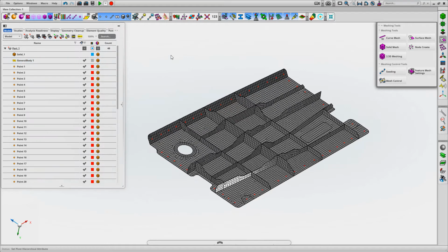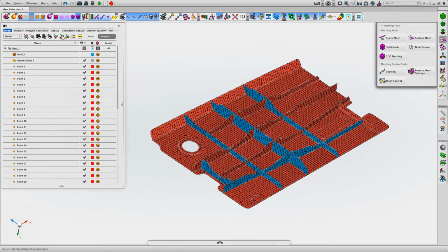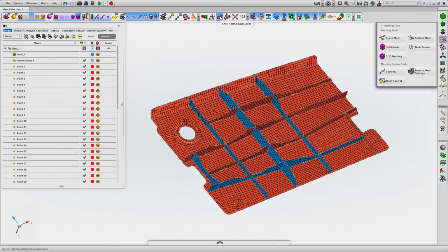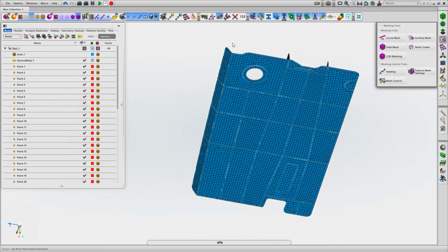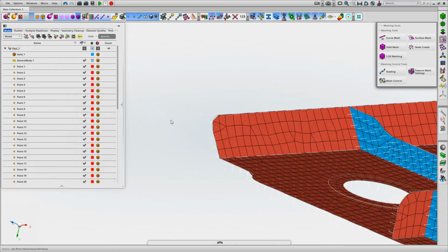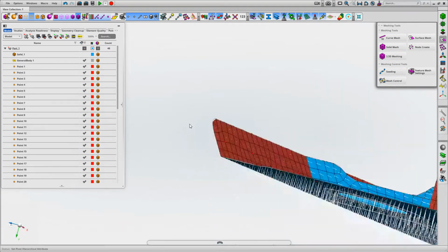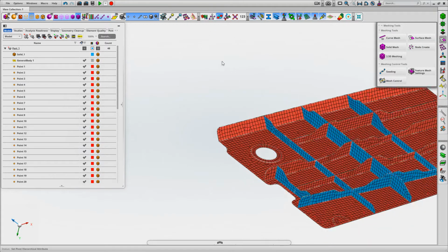If I show the geometry, we're now going to look at the shell normals. Each shell element has a normal direction. Before we look at the directions, I'm just going to look at a color code. This button on the top, shell normal dual color, shows us one face. Let's have a look. The bottom face is shown in this pinky red color, and the top face is shown in blue. Before we worry too much about directions, I like to get the model consistent.